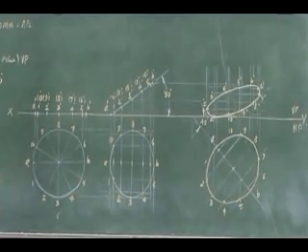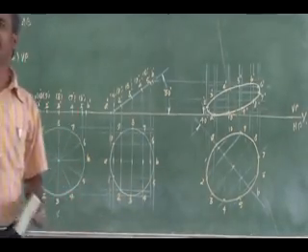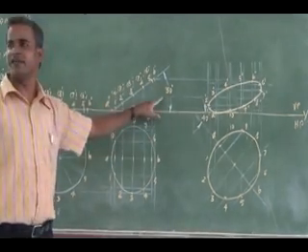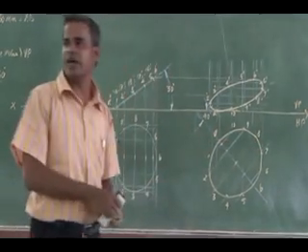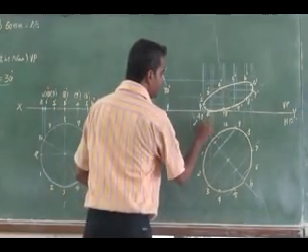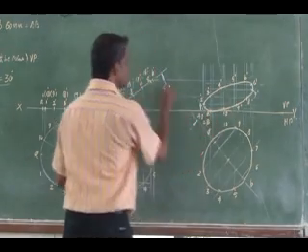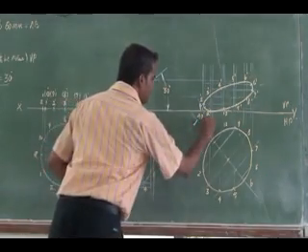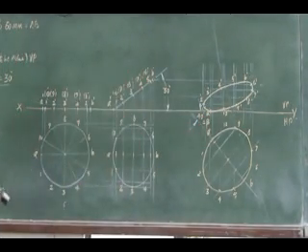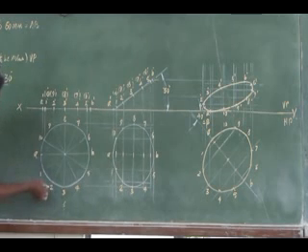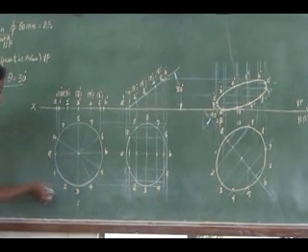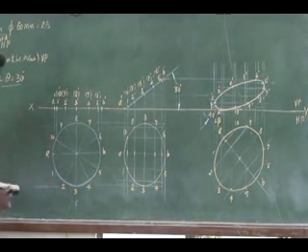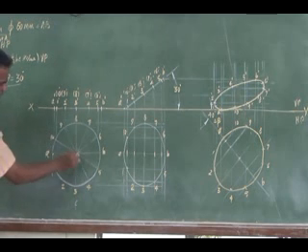Then the given data, you have to dimension it. The given data: diameter 30, diameter 60, then the angle given is 30, we dimension. This is 40, we dimension. This 40 is nothing but my beta, and this is my theta, right? So it is an apparent inclination beta. See here, this diameter I have to dimension. The circle diameter I can dimension either like this, or from the center.